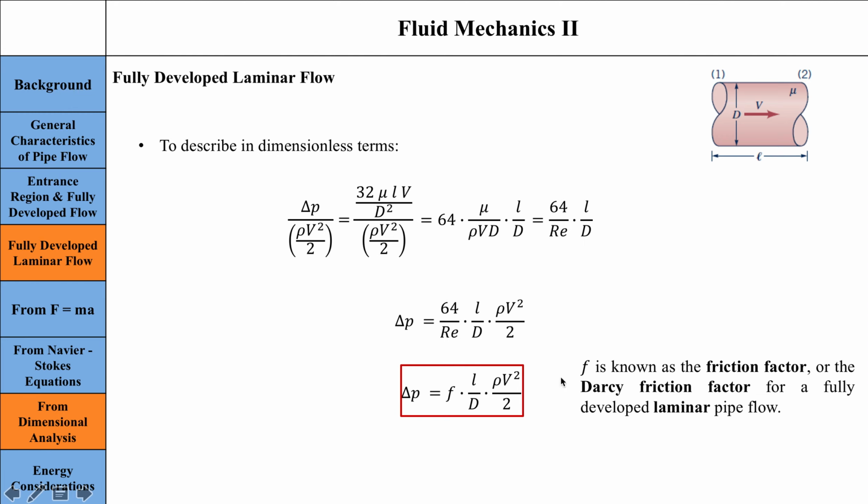The Darcy Friction Factor basically predicts the energy loss within the pipe based on the velocity of the fluid, based on the resistance due to the friction, due to the viscosity of the fluid. And make sure you spot that this friction term is not constant, okay? If the Reynolds number changes here, the friction term is going to change as well, because it depends on whether the flow is laminar or turbulent.